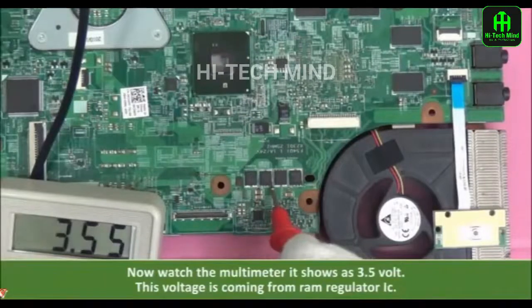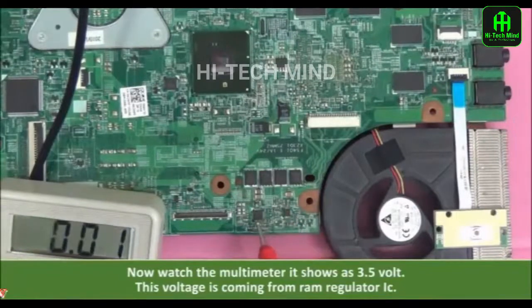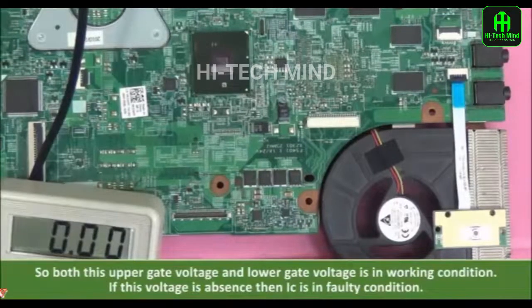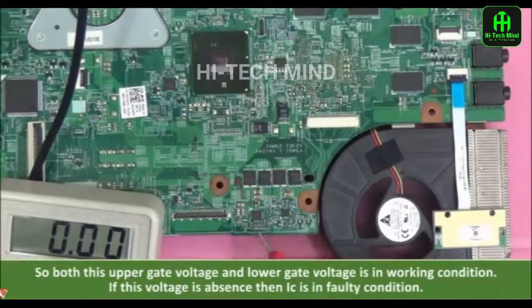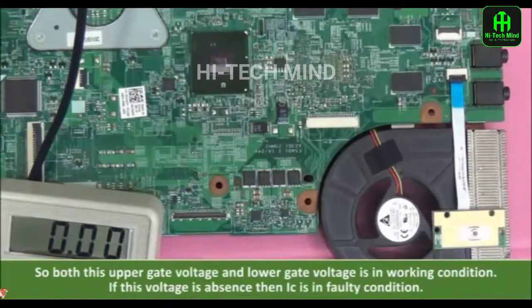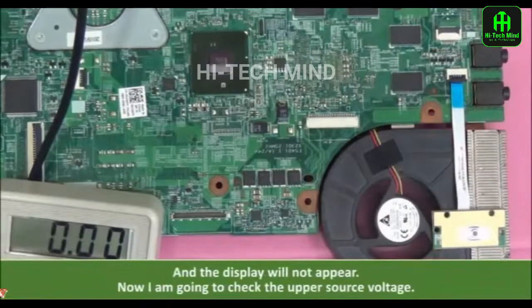It shows 3.5 volt. This voltage is coming from the RAM regulator IC. So both the upper gate voltage and lower gate voltage are in working condition. If this voltage is absent, then the IC is in faulty condition and the display will not appear.